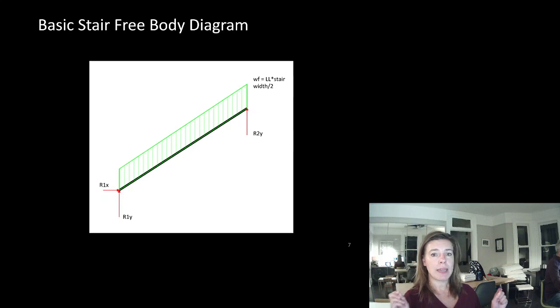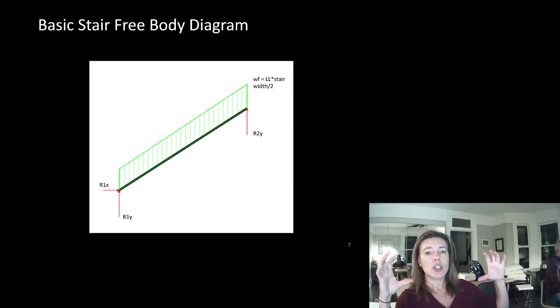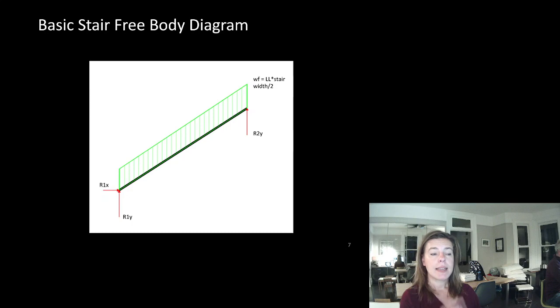If you try to do pinned and don't allow any movement at one end, in the length of movement, you can stop the truss's ability to deflect, which actually imposes very high compression and tension forces in your top and bottom chord. Stairs, if you lock these in as a pin instead of a pin roller, you can actually develop very, very, very high reaction forces.